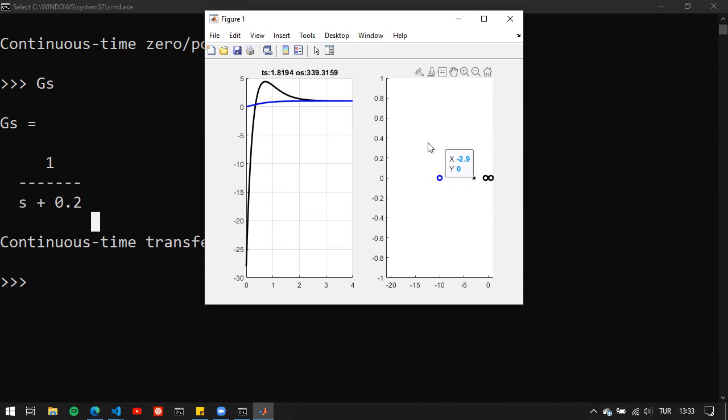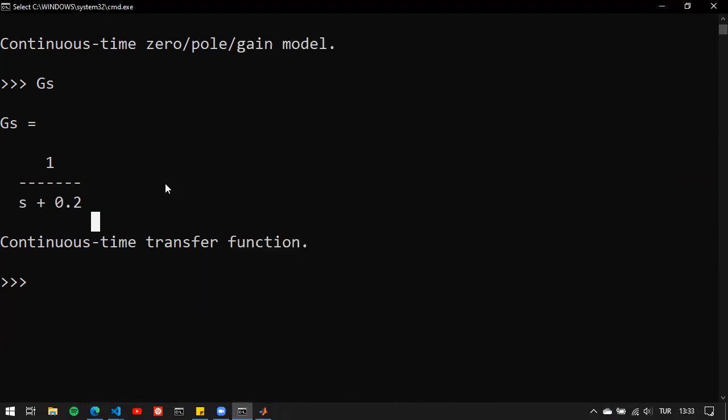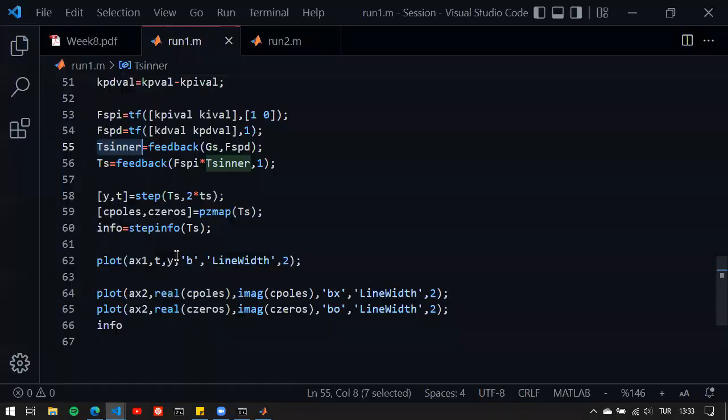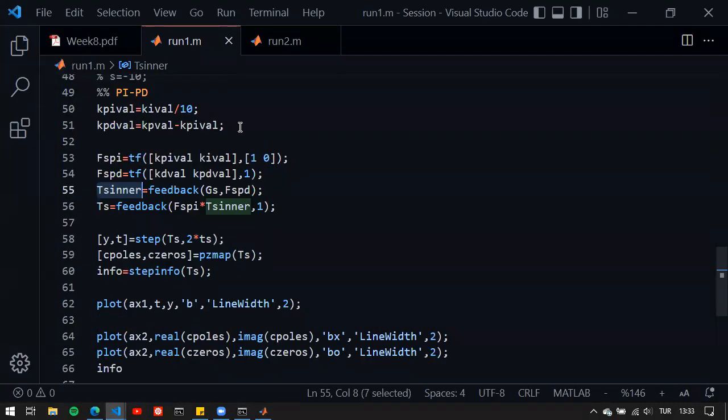Therefore, it's really easy. You don't really have to design the controller from scratch. You have a PID controller, take the proportional part, divide it into parts where you decide on the zero of the PI controller, and then you can just use the relation and the fact that the sum of the proportional parts of the subcontrollers in this case is equal to the original PID Kp value.